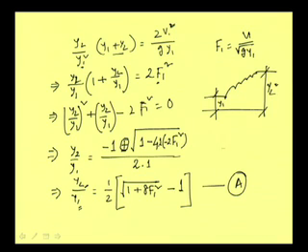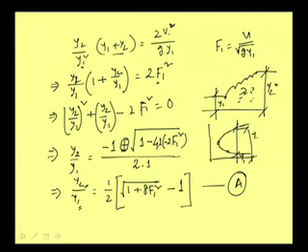And we know that when we draw the specific force diagram, energy is not equal between this point and that point, because there is a lot of loss of energy in this portion. So, energy is not equal, but we are starting from the specific force equation, with the condition that specific force at upstream and downstream are equal. So, this y1 and this y2 we are talking about. These are for the same specific force.